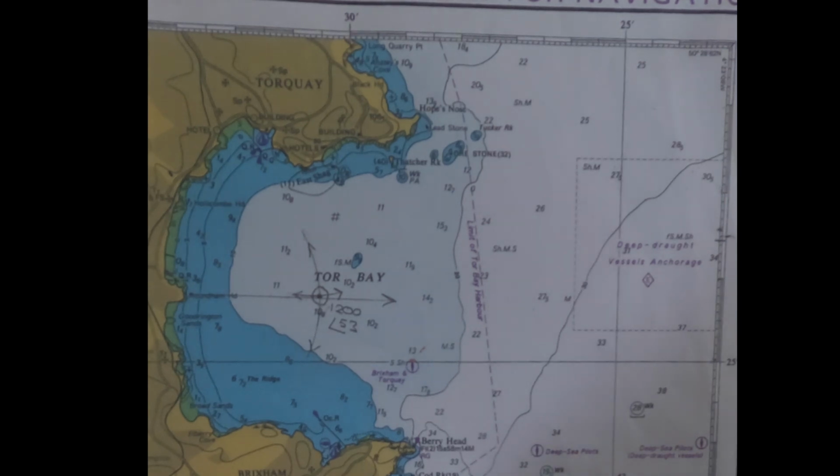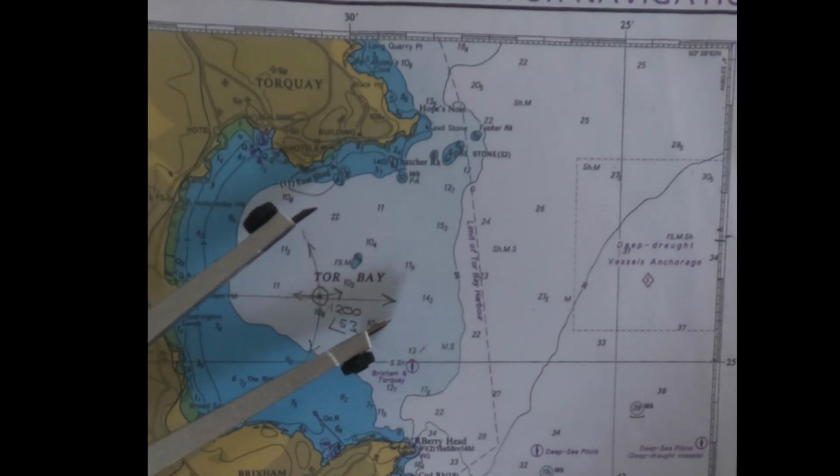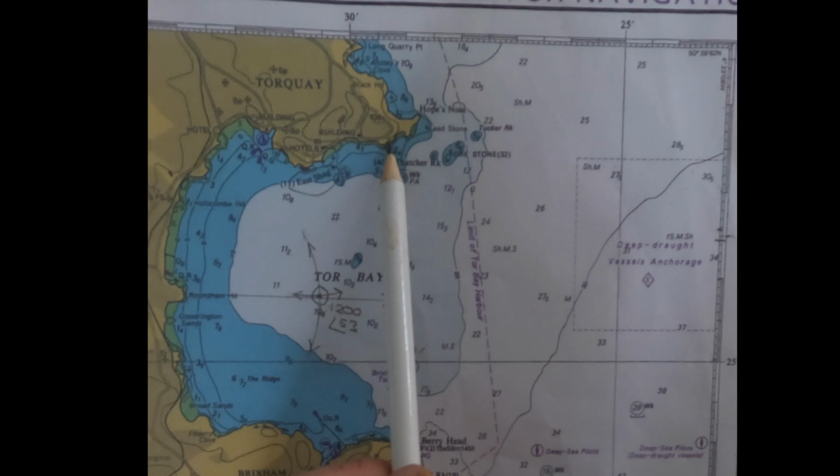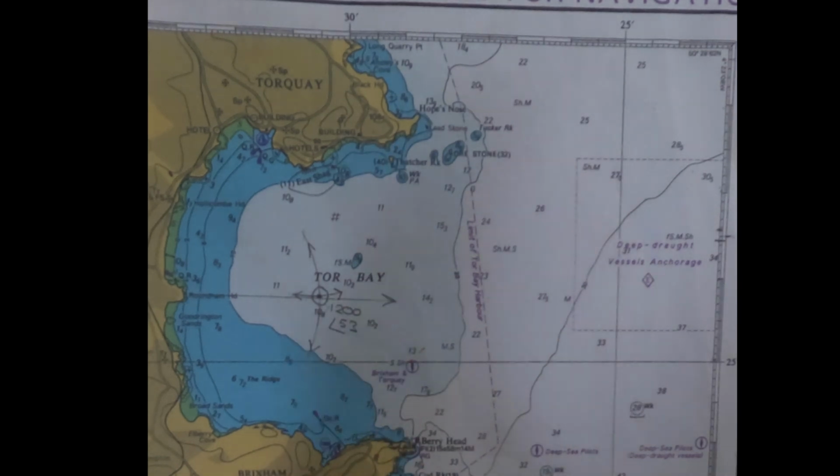So to recap, VRM is much more accurate to use and easier to use, because you can just measure the distances on your VRM, then use your dividers. Make sure you've got a nice pair of dividers. Use your dividers, mark off where you are. You can use bearing lines. Bear in mind, if we are going to use the headlands, we've got to move them in half a beam width, so we need to know what the beam width of our radar is.